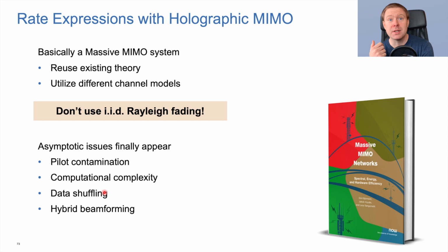And in 5G we will soon see digital solutions being utilized, also in millimeter wave frequencies. But eventually, when we are building very large arrays, you will have maybe 100,000 degrees of freedom, and you won't need all of them. So probably it will not pay off to have the ability to control all of them. So that's when hybrid beamforming like solutions can be implemented as well, but probably using metasurface technology instead of phase shifters, which is just a very bad solution in order to get an efficient operation because of all the losses.